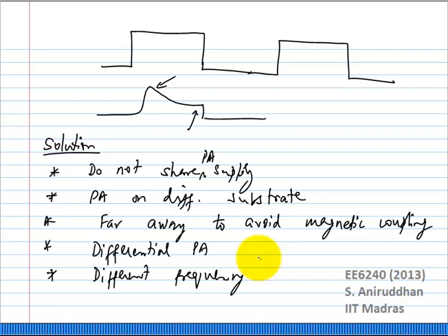However, the VCO itself need not operate at the transmitted frequency, because we know of many ways to generate different frequencies once you have a certain frequency reference. So you can use different frequencies for the PA and the PLL.